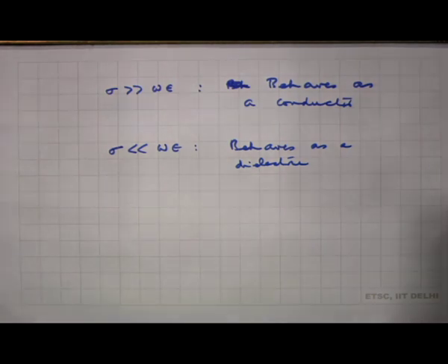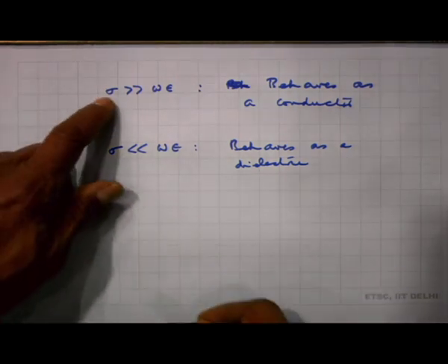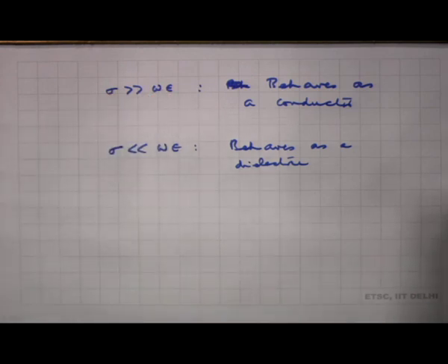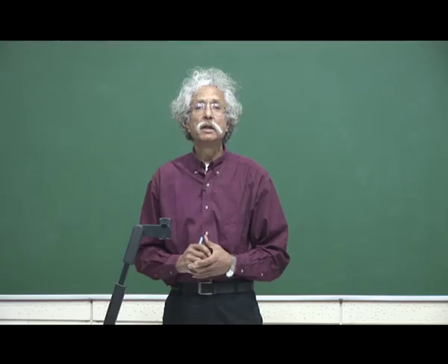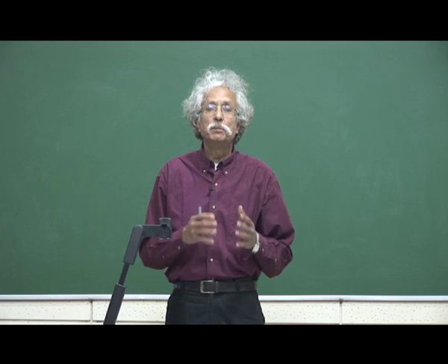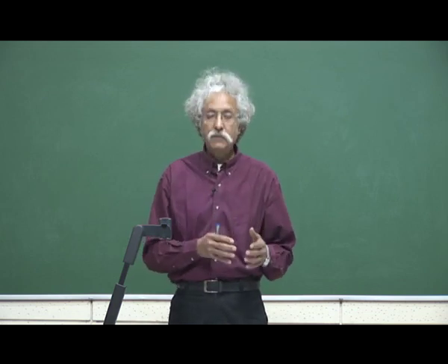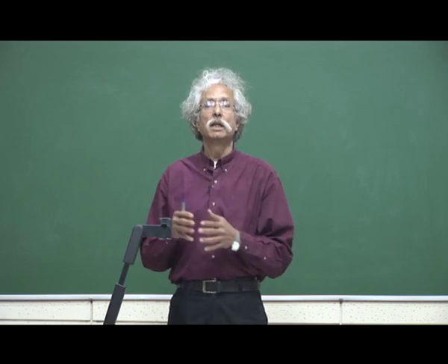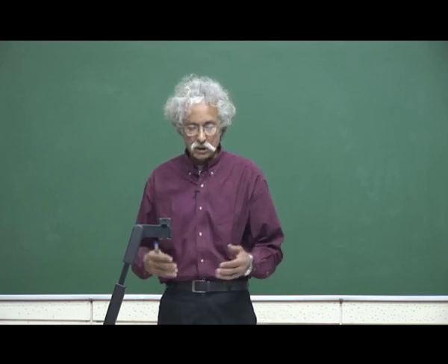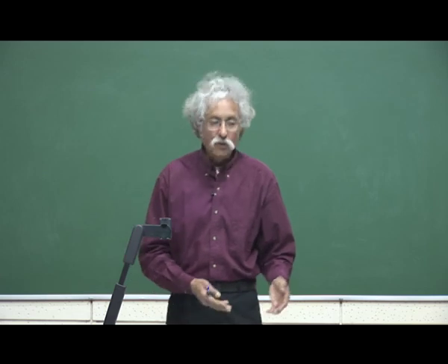So, depending on the frequency and the properties of the medium in terms of conductivity and epsilon, a medium could behave as a conductor where the conduction current is much bigger than displacement current, or behave like a dielectric in which the conduction current is negligible compared to displacement current. So, I can have both these limits, and it depends on frequency.